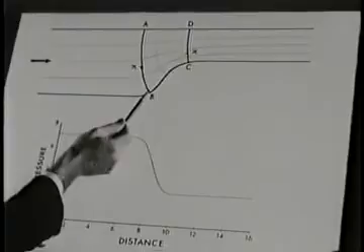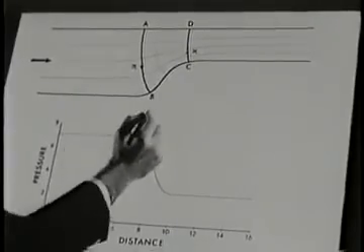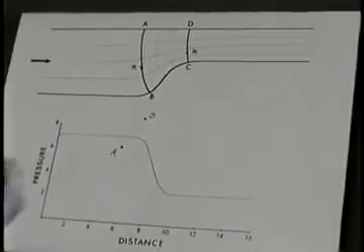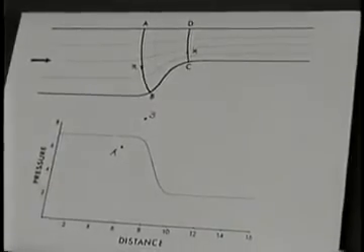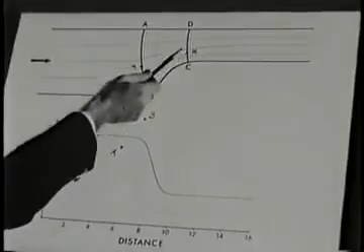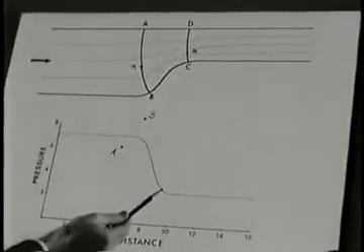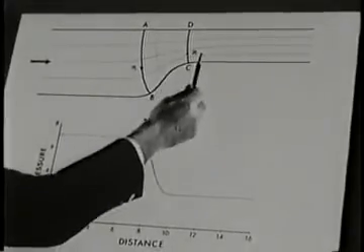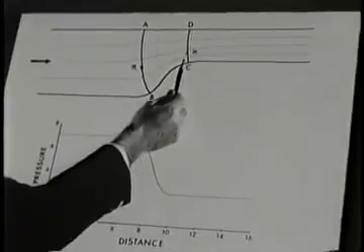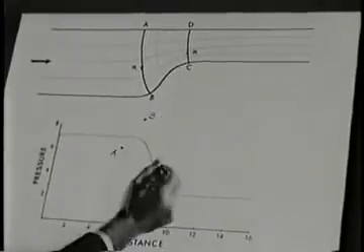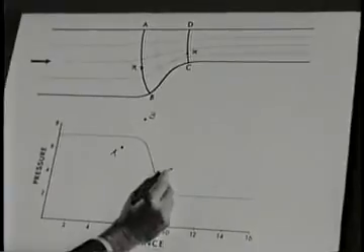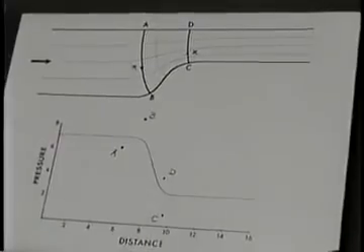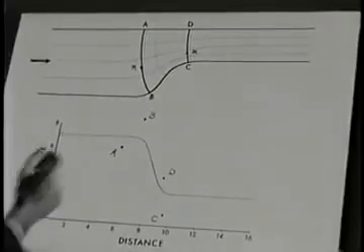Similarly, the average pressure on CD will be only slightly greater than the downstream pressure. Again, though, because of streamline curvature, the pressure will increase from C to D. So the pressure at D will be greater than the average, while the pressure at C will be less than the average. So the pressure on the curved wall rises to a maximum at B and then falls to a minimum at C. While on the straight wall, it falls continuously from A to D.